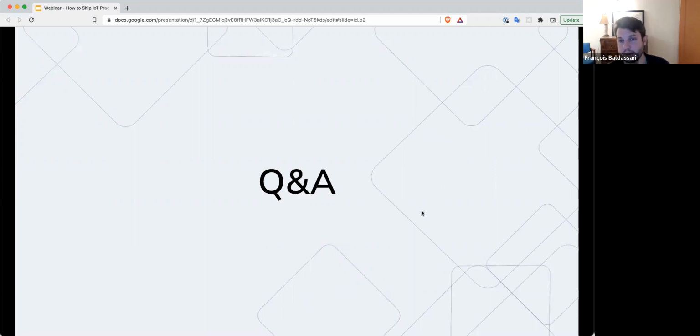Jelmer, and again, I'm probably butchering a lot of your names, so I apologize for that. Asks, how do you do remote debugging with a device that has low power and spotty connection? Great question. We do this a lot. At Pebble, as you can imagine, we were on a super low power, battery powered device that was only connected when the user was near their phone. So the answer is actually very straightforward. You do it asynchronously. You store the data on device while the device is disconnected, and you upload the data when the device is connected.